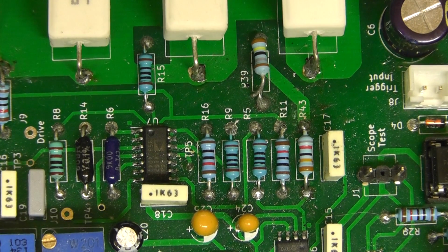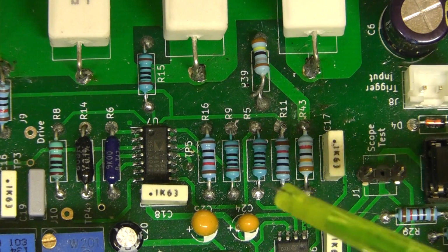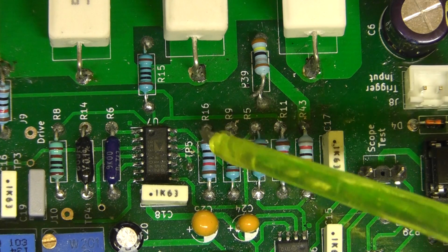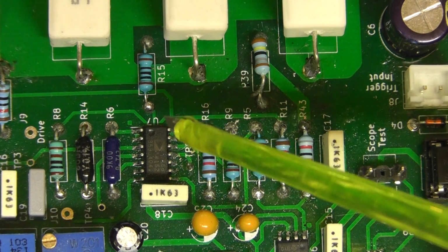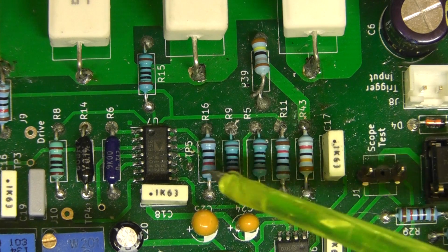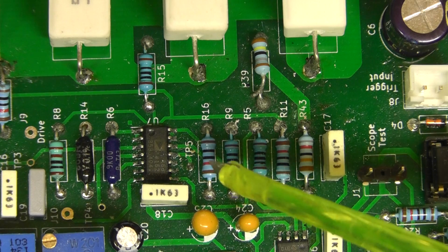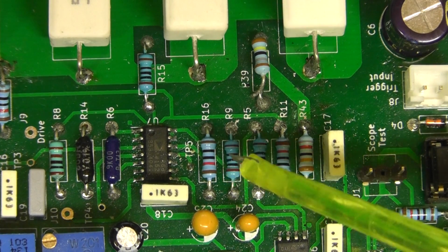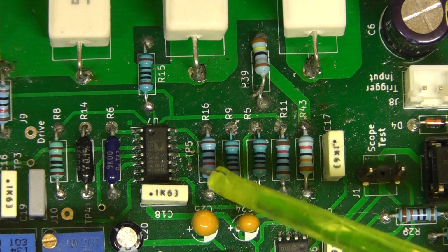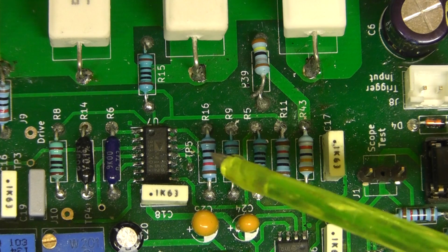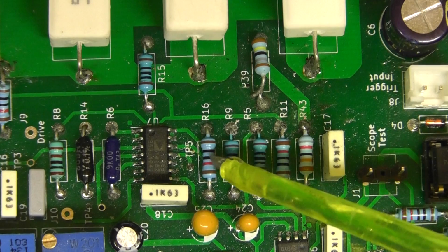I'll just point out the area of the board where we have that earthing wire coming through. It's actually there next to the operational amplifier, that's U7, and you'll see there's a little test point labelled TP5, which is plated through a hole to the other side of the PCB. It's a ground point, so all we've done is put a wire through that test point to the other side of the PCB that's then anchored onto that additional copper, and we solder it on both sides of the board.